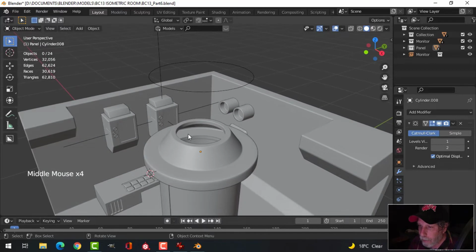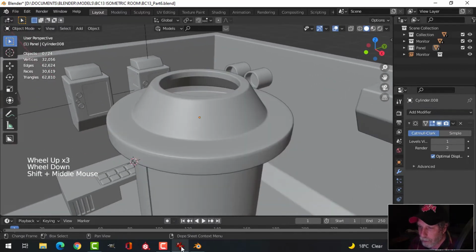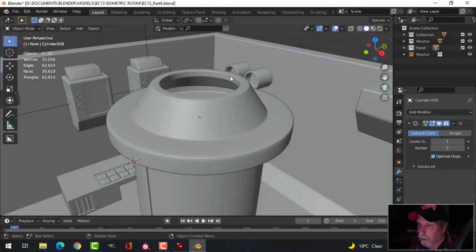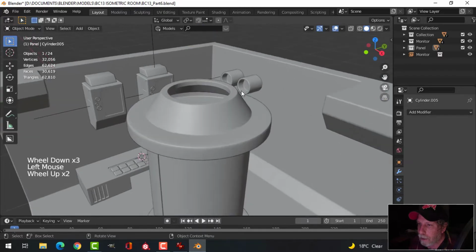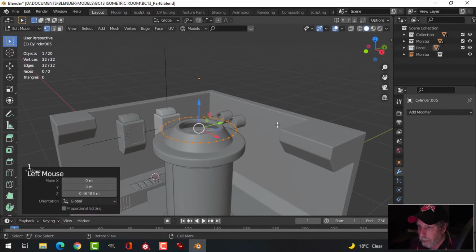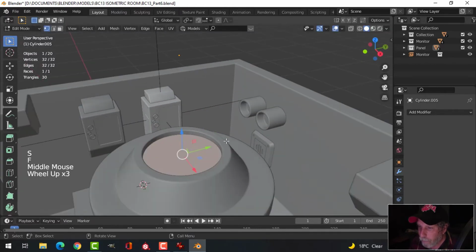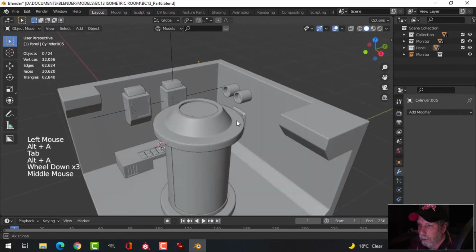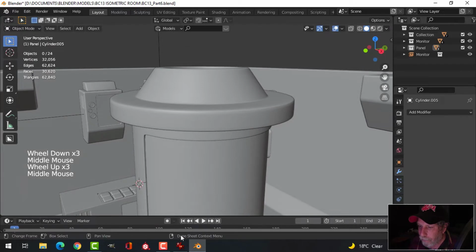And then we're going to make another piece that goes in here to make like the end of it, the cap here. I'm going to make it as a separate piece so I can do a cut. Now, you know, sometimes I would use maybe Substance Painter to do that, but I'll do it as a separate piece of geometry. So let's just take this piece now that we have. Go into edit mode. Let's pull it down, scale it. I think I'm just going to press F to make a face for now, and just leave it there and come back to that thing later.